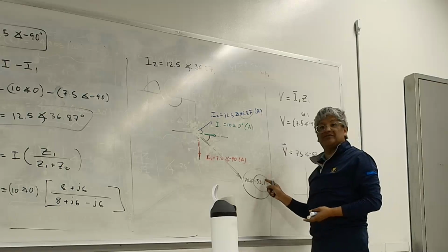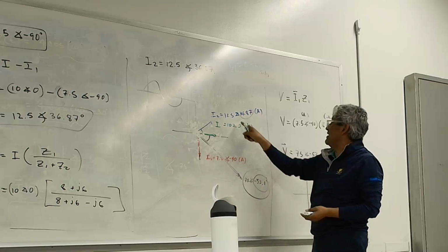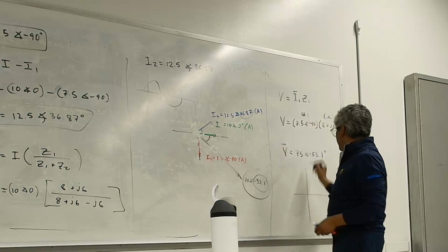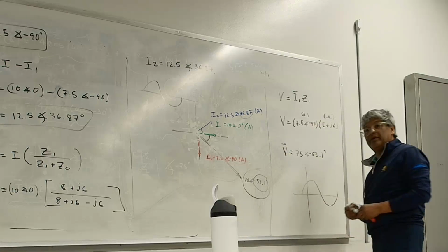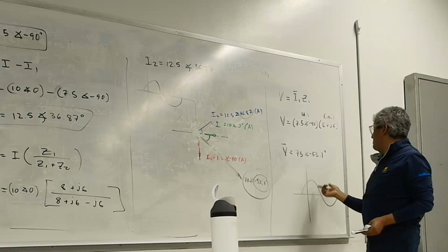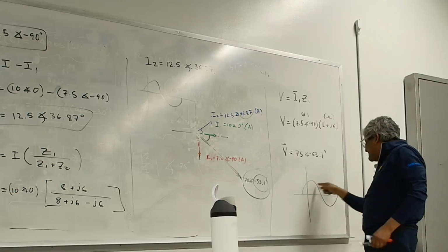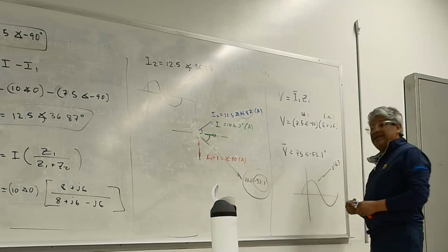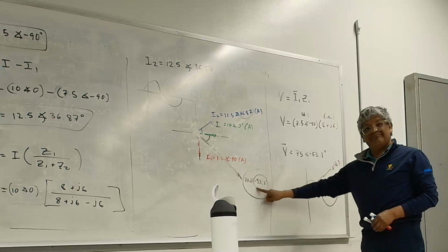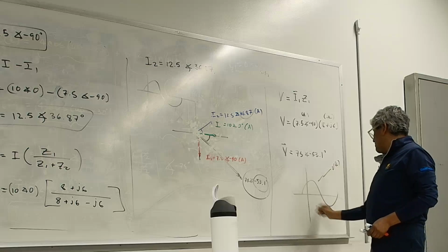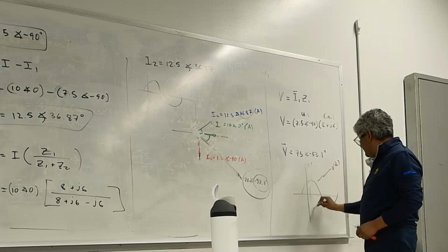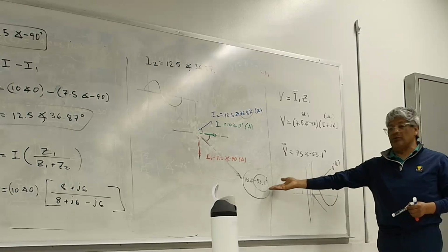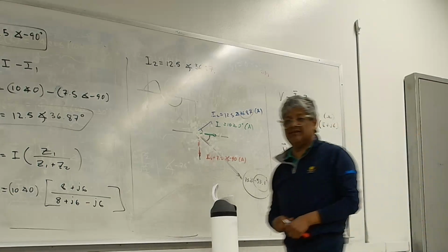Yeah, I can subtract 53, plus 53, but I've got plus 53 right here, right? It's the same thing, once again, as this. If you have a scope, and say in the scope, you say, I want this signal, whatever the signal is, let's call this signal b(t). I want to make this signal the reference. All you do is move the line until you get it to the peak, and this now becomes your reference. That's basically what we did. You subtracted or added the angle.